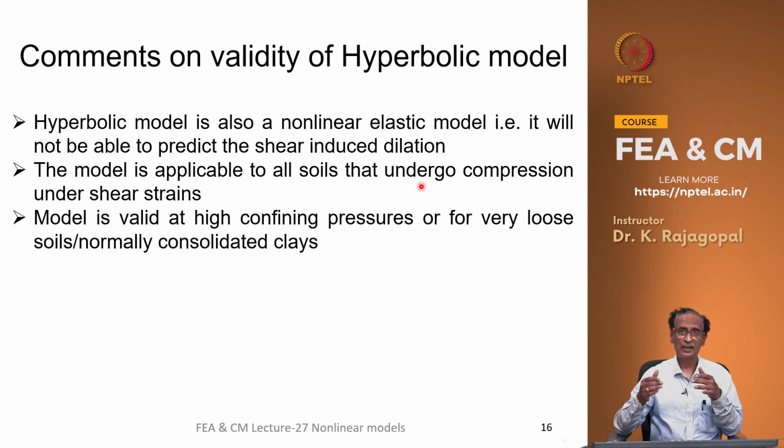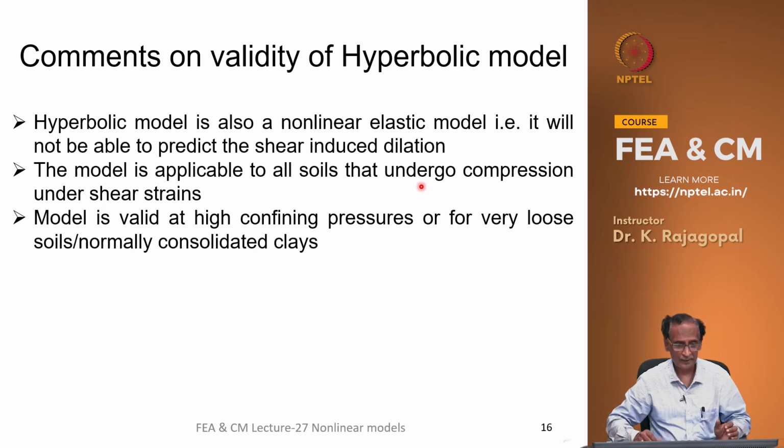Even at very high confining pressures we can apply the hyperbolic model, and this model is applicable at high confining pressure for very loose soils or normally consolidated clays.